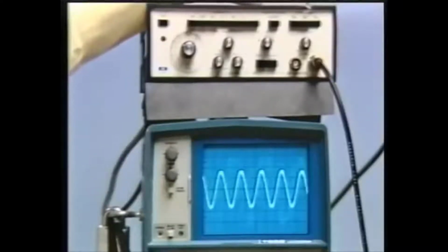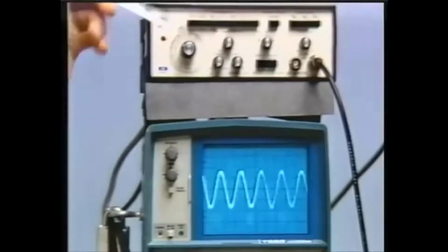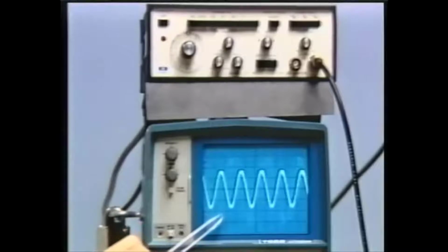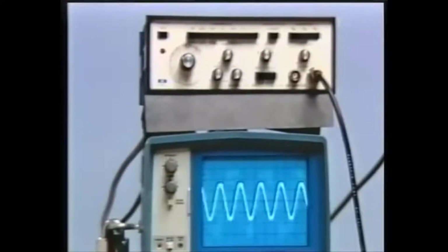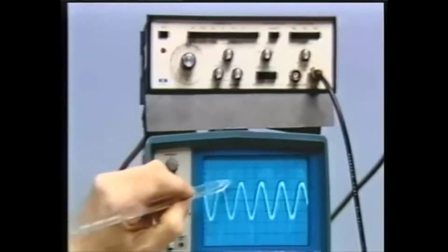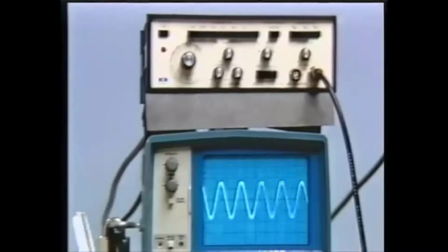Okay, so maybe we can just vary some of this and see what a little bit of it looks like. All right. What we have displayed at this point is the effect of pushing the sine wave button, and so displayed down here is a 500 hertz sine wave. In fact, let's listen to that. Great. And the scope is set to have 1 millisecond for each division here.